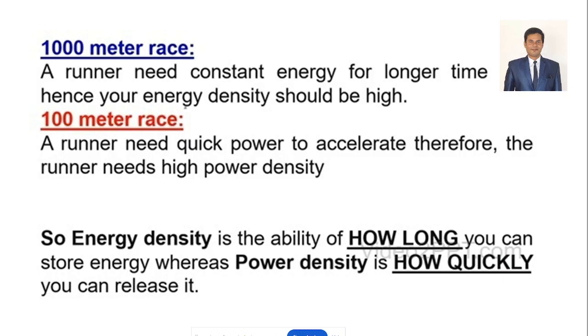So hence your energy density should be very high to have longer times or longevity of supplying the energy, right? Especially for the batteries. It doesn't matter for capacitors, okay? Don't bother with the capacitors. Power is more. We're talking about power density being very high in the capacitors, whereas in the batteries the energy density will be very high, right?